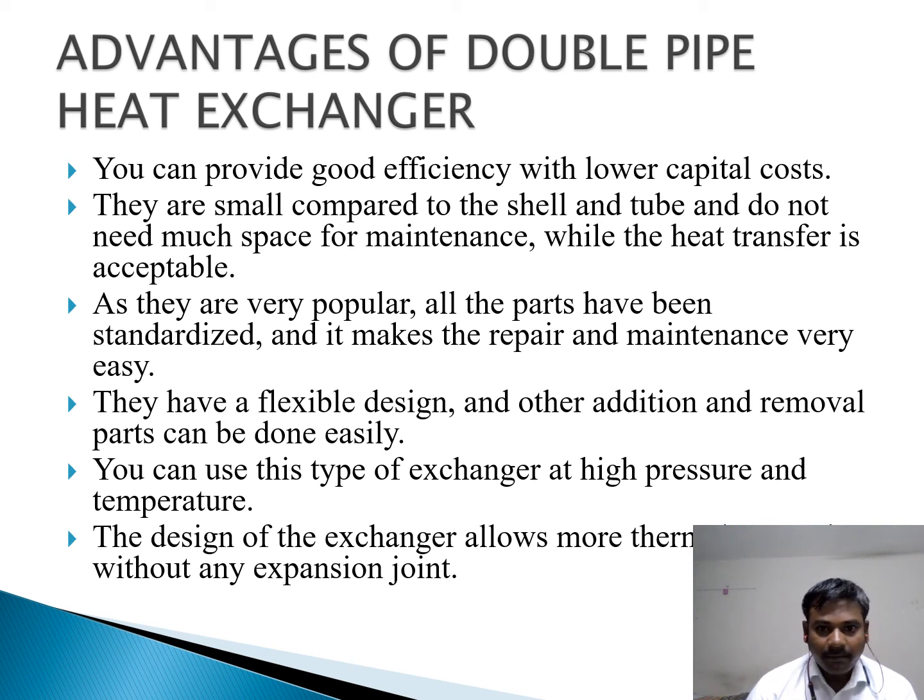As they are very popular, all the parts have been standardized, which makes repair and maintenance very easy. They have a flexible design, and additions and removal of parts can be done easily. You can use this type of heat exchanger at high pressure and high temperature. The design also allows more thermal expansion without any expansion joint.